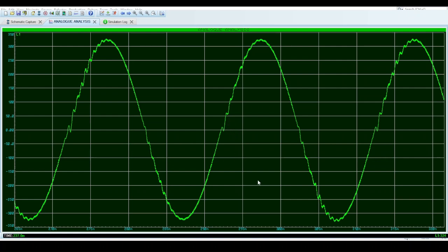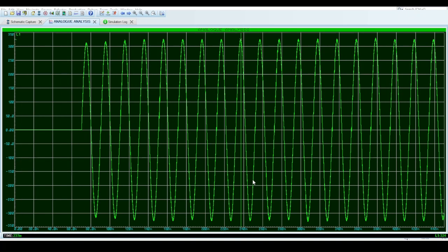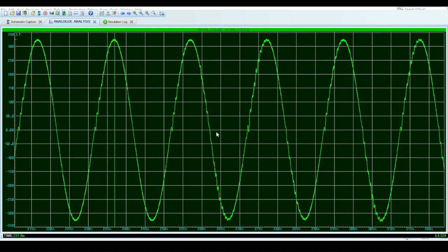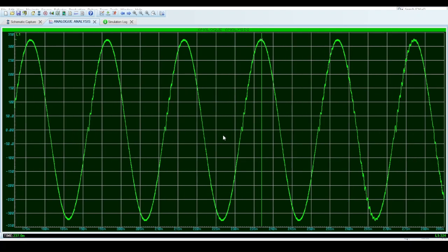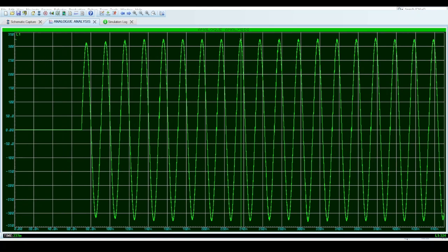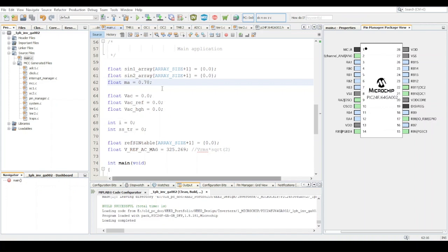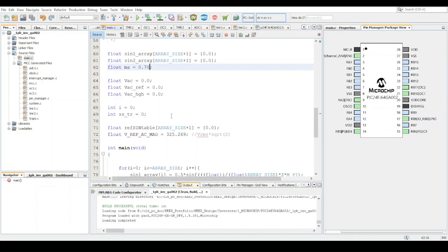And as you can see, the sinusoid is kind of squiggly. Well, that is owing to the poor resolution, only changing 50 times every 10 milliseconds, or 100 times over a 20 millisecond cycle. So that could obviously be greatly improved upon. And yeah, that's about it with this particular method, the first method, which I would say is a bit on the easier side.